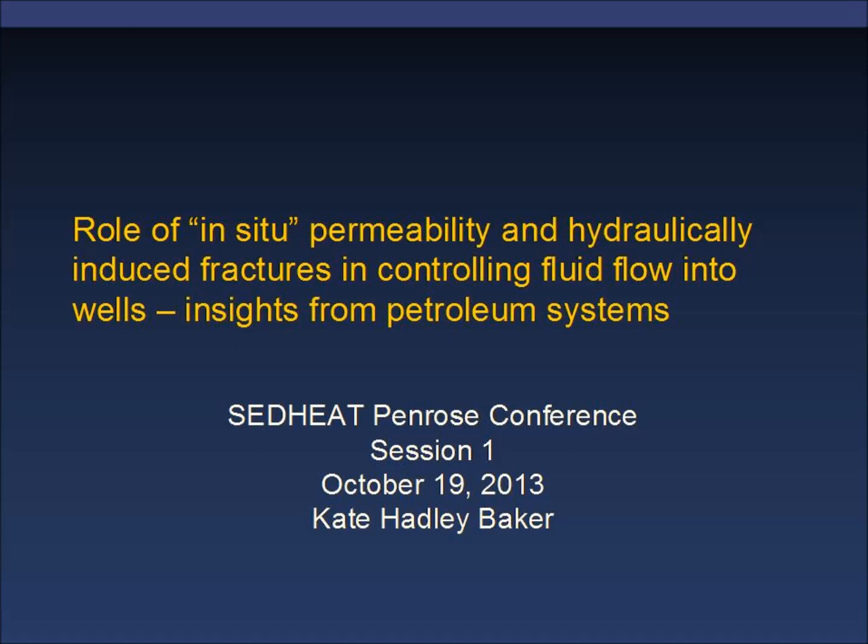Originally, I was supposed to give a keynote for session 4, so the focus of my talk is largely going to be on in situ permeability and hydraulically induced fractures in controlling fluid flow into wells and the insights from petroleum systems that bear on that. And in situ is in quotes to refer to pre-drill permeability of whatever origin, including but not limited to matrix, porosity, vugs, and fractures at all scales, as distinguished from drilling-induced or hydraulic fracturing that we do, things we do during the completion of the wells, okay?